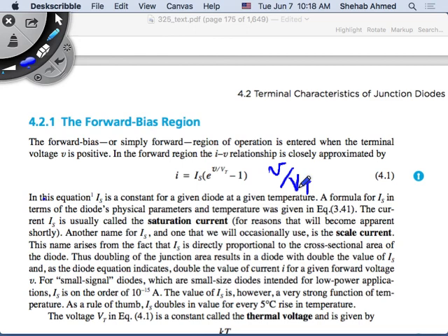Basically the constant that controls the diffusion of the current versus the constant that controls the drift of the current, mobility. So it's diffusivity over mobility. That was VT. And remember, mobility was temperature dependent, which means that VT was temperature dependent. If it depends on a temperature dependent variable, then it's a temperature dependent value.